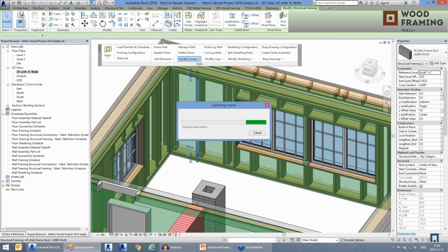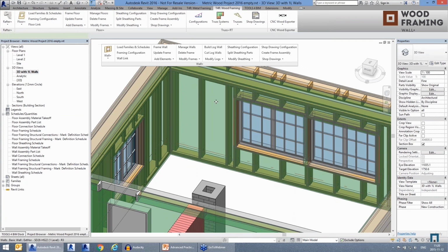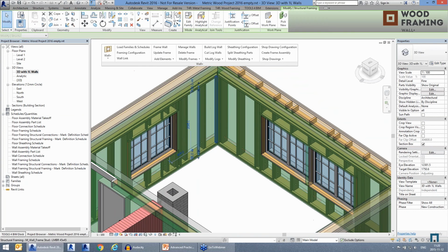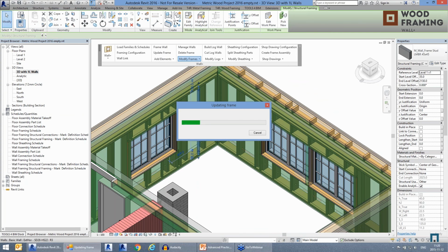At the same time, you can align not just frames from the same wall. If you use, for example, our floor framing, you can see that those frames were aligned. The same we're going to make with this wall segment. So in such case, you can align not just elements from the same wall, but at the same time you can align elements with the existing floor, or with the existing maybe trusses or rafters.